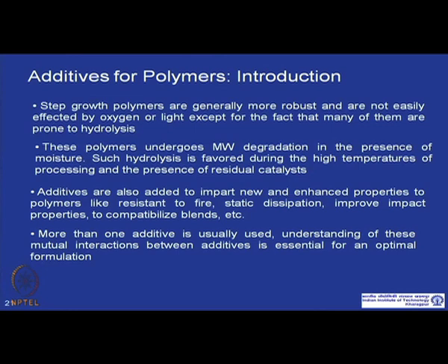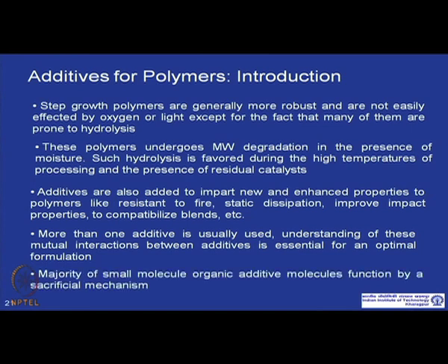And typically in a polymer formulation, more than one additive is used, and so an understanding of the mutual interaction between these additives is essential for making optimal formulations. And generally these small organic additives work by a sacrificial mechanism.